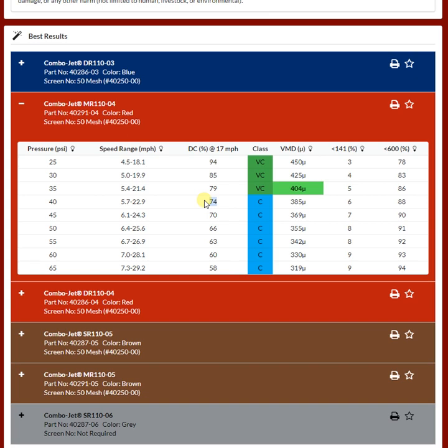So below 40% duty cycle, you can imagine every second nozzle is working in pairs. So they're pulsing in pairs in each other's off cycle. If your duty cycle is ultimately too low, for an example at 5.7 mile an hour, we're at a 25% duty cycle. So one nozzle is pulsing 25% of the time, and the next beside it is 25% of the time in the off cycle. The troublesome part is that if you add those two together, you're only spraying half the time.